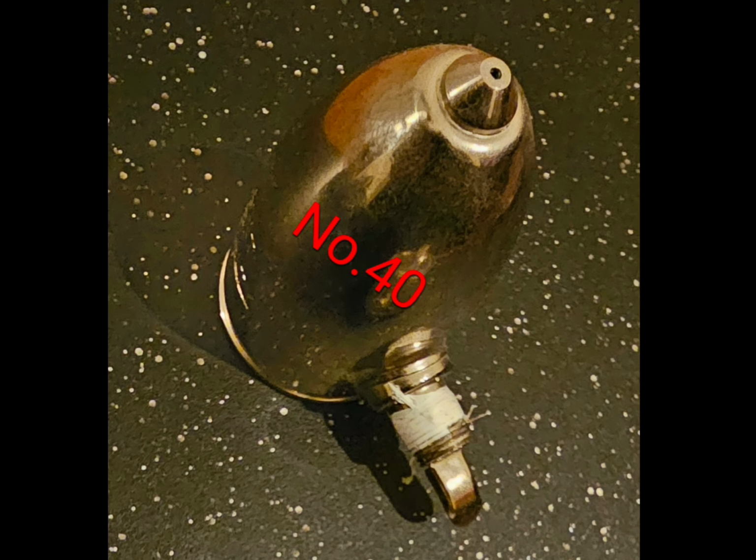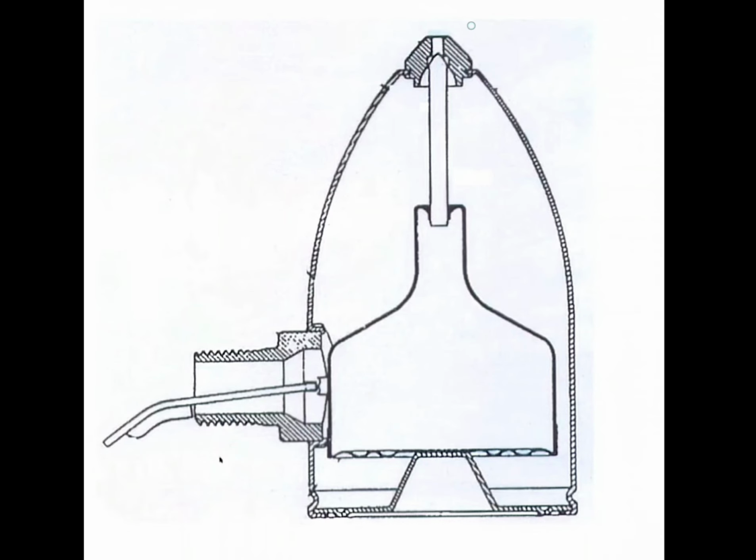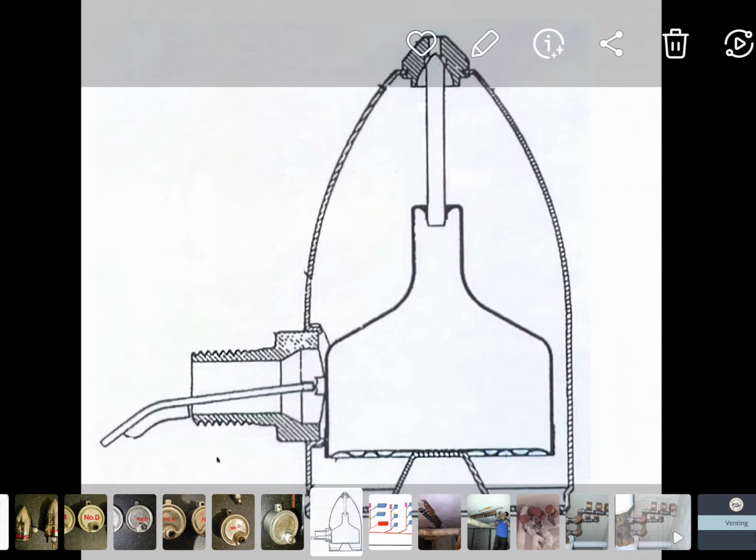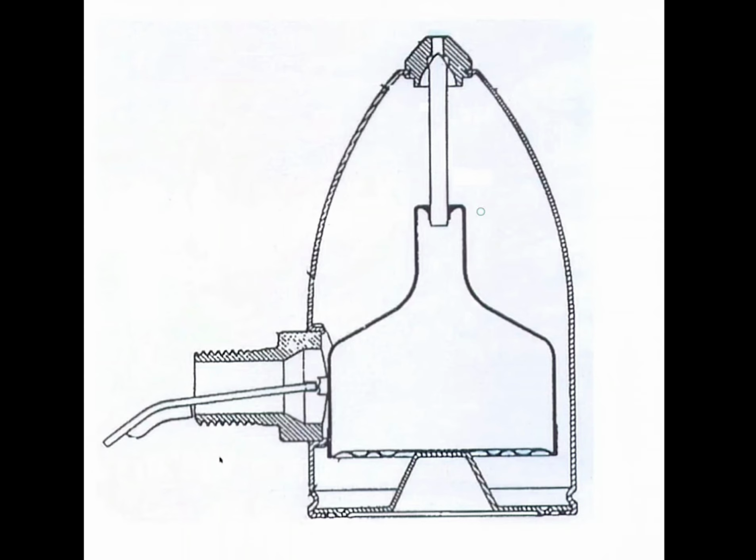So what I'm saying is if you don't have the proper wind capacity or the outlet capacity, it doesn't matter how much you blow through here, you're just going to pressurize the inside of the valve. In order for this to do what Dan is describing, it needs to have momentum moving through here. You don't even need pressure. You just need a large amount of wind momentum moving through here, and that would cause that to go up. But just the way this is constructed, this doesn't happen on Hoffman air vents, not on the 41. There are Hoffman air vents made for steam mains that have much larger openings where that is applicable, but not on this one.